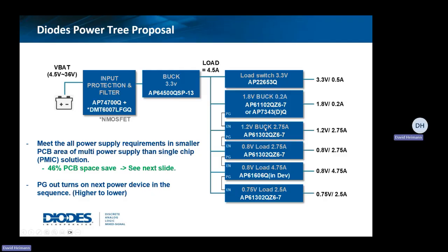we did also offer the ability to second source most of these DC to DC converters, because the bulk of our DC to DC converters in this family will drop into typically a TI socket, but there's some MPS, there's some Richtek. There's a number of different suppliers where we will have a pin-to-pin drop-in, and in some cases a pin-to-pin and BOM-to-BOM drop-in for the other converter. Okay.